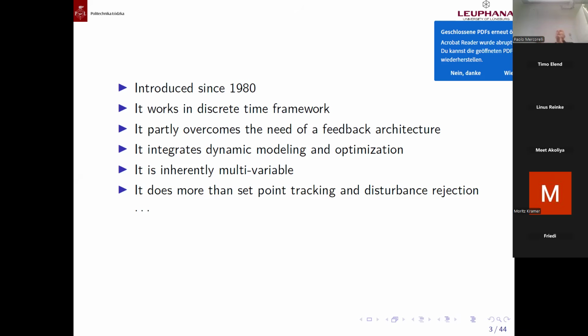And the feed-forward control strategy or architecture. And this method here combines them. Now, this is written, he overcomes. I copied from a book, I don't like it, but in any case, it is correct. I mean, it integrates a feed-forward within a feedback. And this sometimes very easily simplifies the architecture of the feedback, because the feed-forward control contributes, in particular in this case, in an intelligent way, to the control.